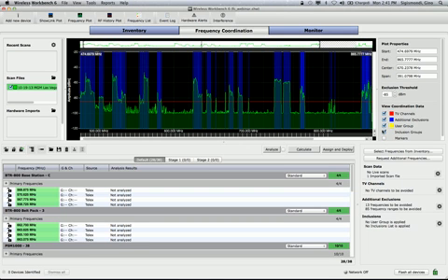The first thing I want to mention is this is what scan data looks like in the application. And the reason it's significant is because it's not just a pretty picture. The scan that's been captured is actually being processed by the application, in addition with this red line, this exclusion threshold, to generate these blue bars. And these blue bars signify exclusions, or where frequencies shall not be put. Now, this is really important because with scan data that has been captured, ideally with the same antennas of your wireless rig and in the same venue where you're going to be operating wireless, we are now instantly avoiding any spectrum that surpasses our RF noise threshold for pain, effectively.